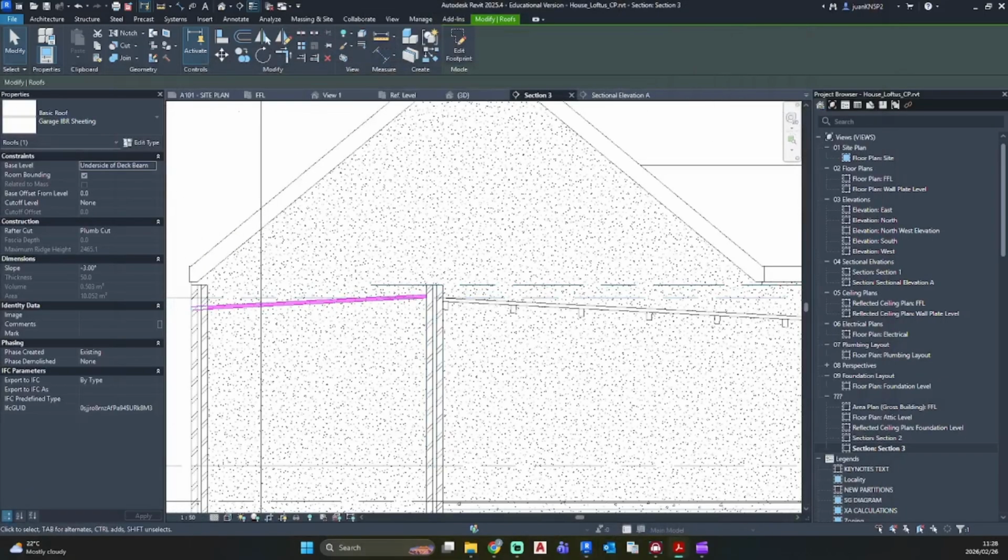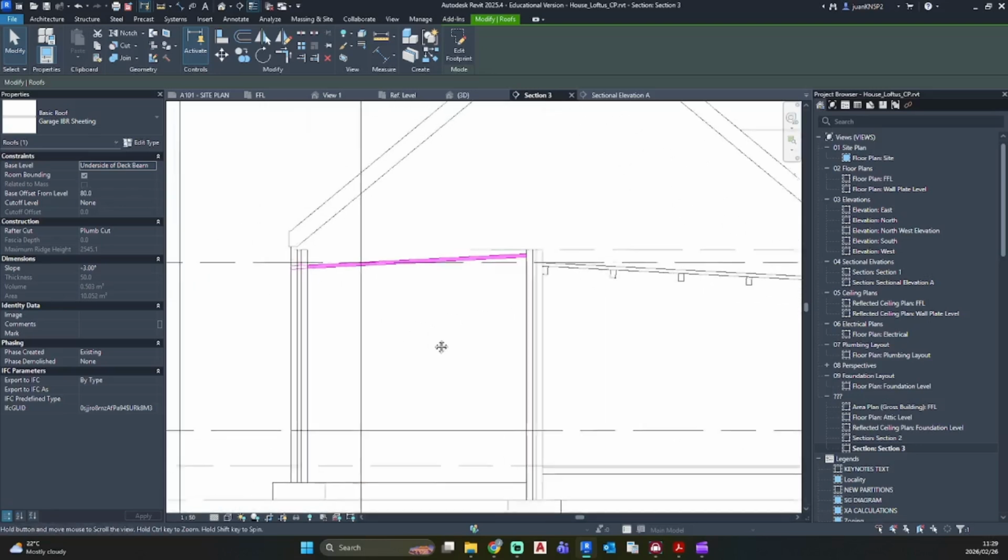So we now need to check our ceiling thickness as well. Ceiling, no ceiling to garage, skim gypsum board on 38 by 38 brandering, 400 centers. Okay, so there's no ceiling thickness given, but a gypsum board ceiling is normally 12 to 16 mil, and we can use that. This is the standard size. So I am going to wing this. Going to move this up.